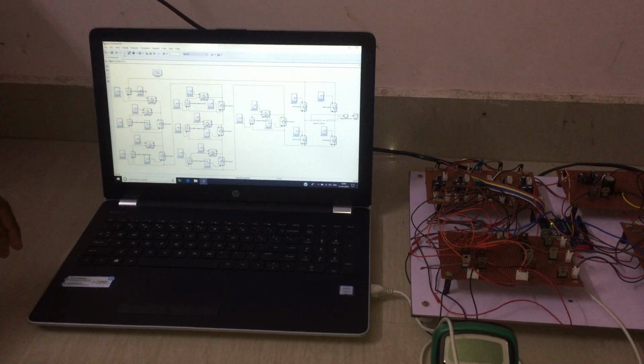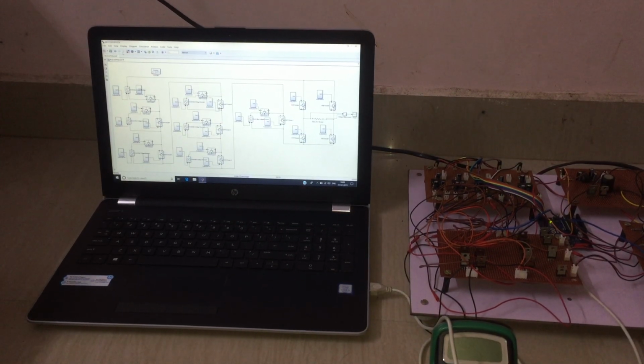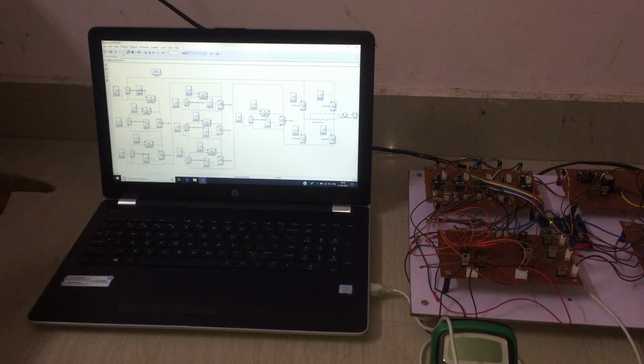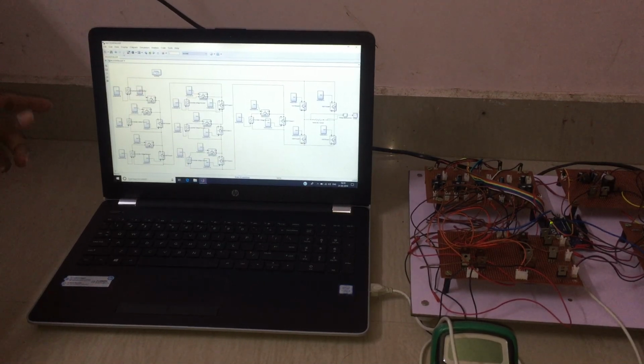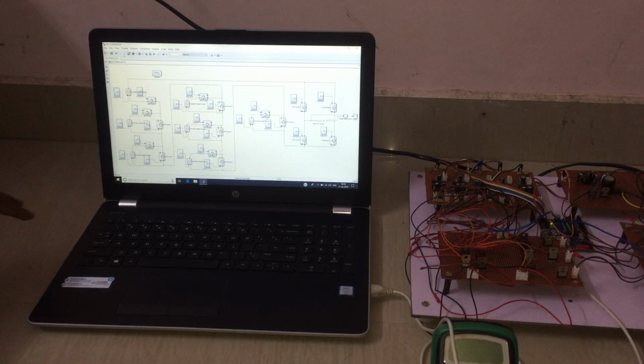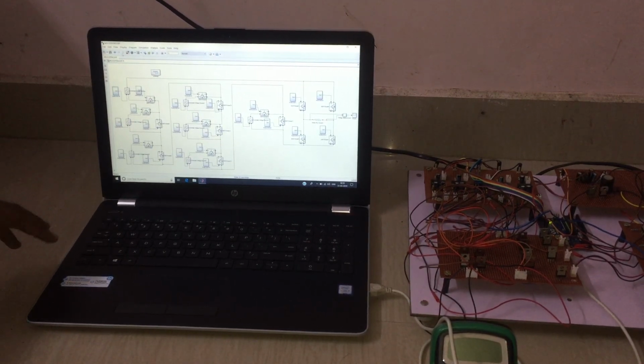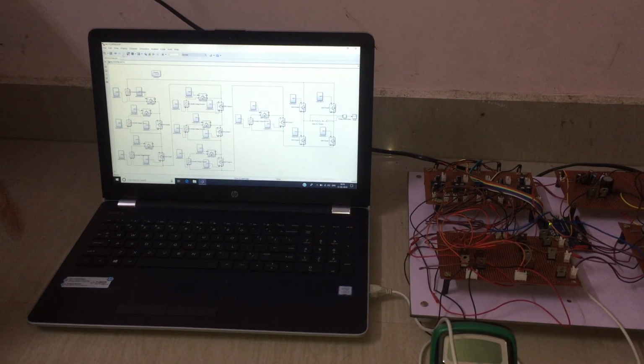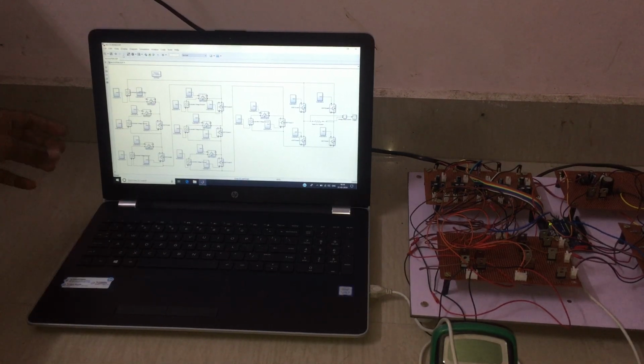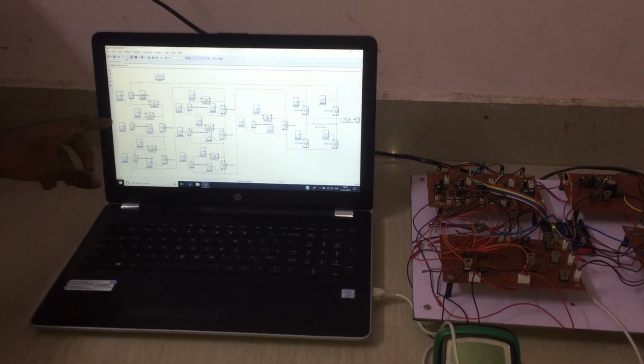In this we have started from lower level inverters, and till now we have completed the 15 level inverter, open loop and closed loop both. The circuit complexity is drastically reduced and it is suitable for medium and high power applications. The THD of the output is quite low when compared with the conventional inverter. Now we are going to see the multilevel inverter 15 level open loop.